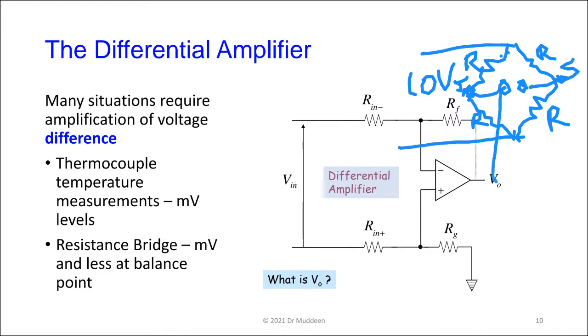So if I were to connect my op amp here, apart from reading the little voltage across here, the non-inverting input is going to be at +5, and the inverting input is also going to be at about +5 as well. That is what we call a common mode voltage. It has to ignore that. All right?